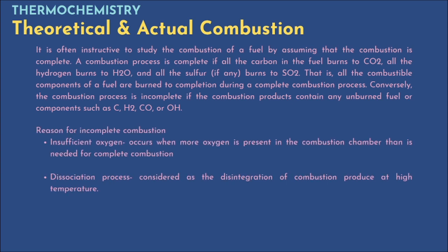Theoretical and actual combustion. It is often instructive to study the combustion of a fuel by assuming that the combustion is complete. A combustion process is complete if all the carbon in the fuel burns to CO2, all the hydrogen burns to H2O, and all the sulfur, if any, burns to SO2. That is, all the combustible components of a fuel are burned to completion during a complete combustion process.